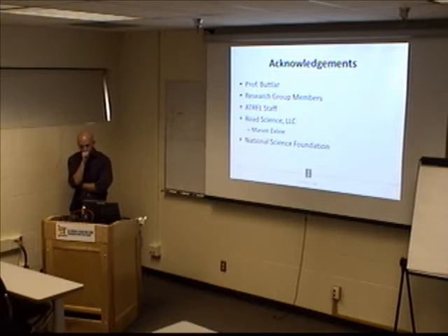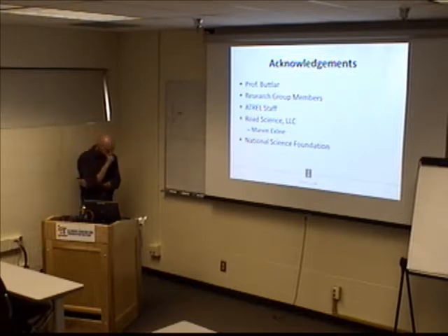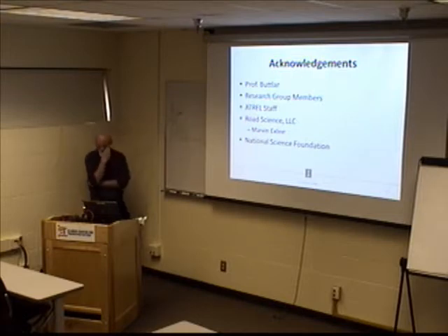We were pretty surprised how low the fracture energy was for the pure binder. We thought it might be a fraction of the mixture, because the mixture derives some of its toughness from the fact that it's a composite. But it was an order of magnitude, or a couple of orders of magnitude, less. So very, very brittle, with very low fracture energy.